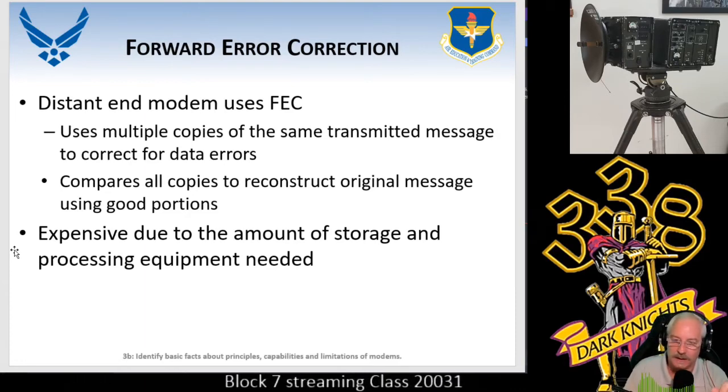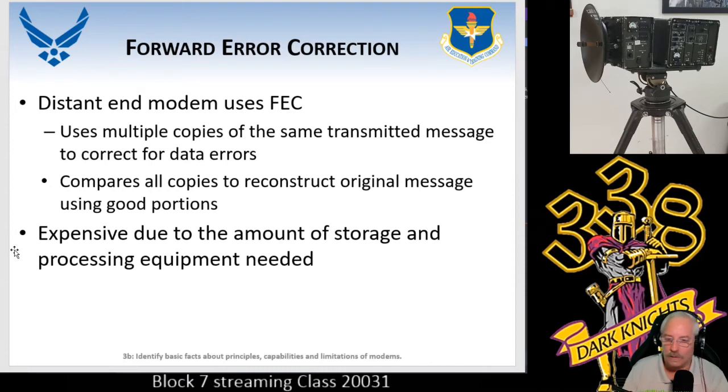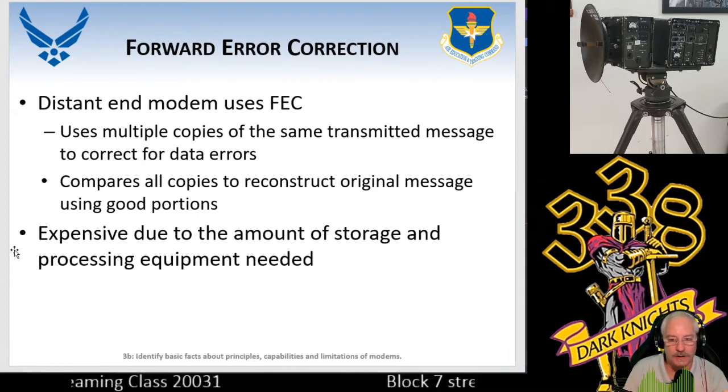When we look at this, we also have something called forward error correction along with the information they're going to be sending, either ASK, FSK, binary, Quadrature, or QAM. Out of those 5, 3 of them are 1 bit per symbol: the amplitude, frequency, and binary phase shift keying. But when you get into the Quadrature and the QAM, it's 2 or more, all the way up to 10.